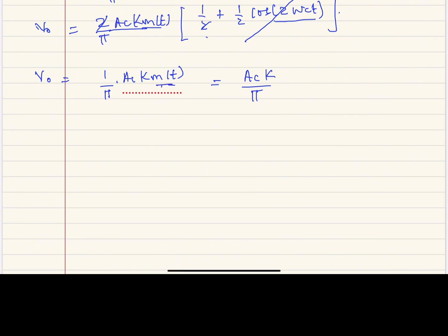And as I was saying during the explanation for the envelope detector, there will be some scaled version. Therefore, you can pass it through a low pass filter again to remove that DC component. This is a DC component, this one.